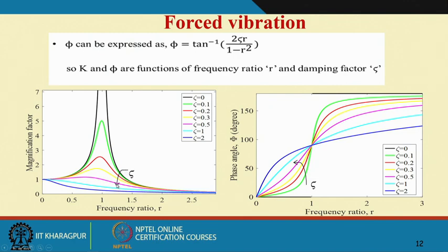Now, this is one takeaway we have from the slide. And you will see for the case of no damping, okay, the phase angle changes by 90 degrees here, and this is a function of the increasing damping.